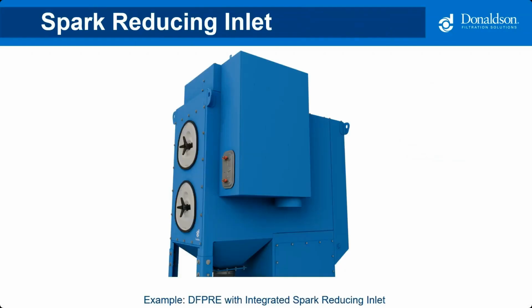Here's an example of a spark-reducing inlet that we use on our DFE collector. So essentially what this does is, as the air comes up from the bottom in the inlet, it forces the air through a tortuous path, and that air will then travel through different directions, which essentially will help knock down the sparks.